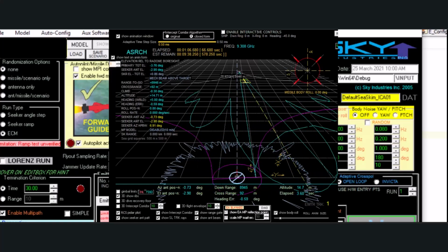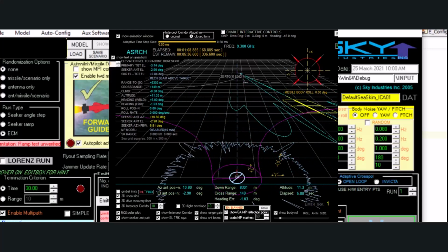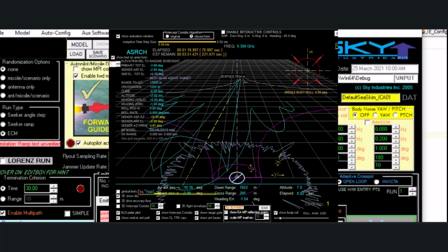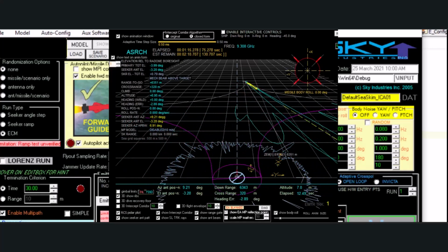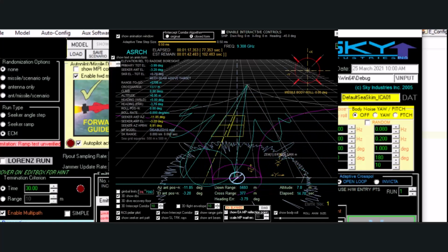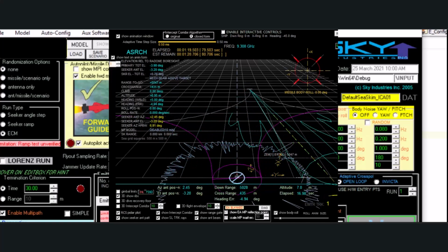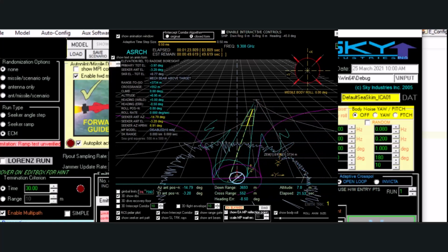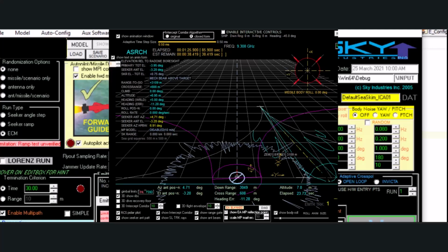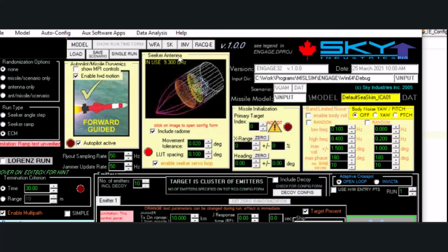But you have to design those yourself. And the default is right, I think. But if you wanted to choose your angle sweep and range sweep, you have to get enough power on the target, so you can't be sweeping too fast. You don't want to sweep so that the half power beam width of the seeker moves faster than the range gates can sweep, right? That's the thinking part, the missile designer part. So if there's no target, it does an angle search and volume search to find something, and when it finds something, it behaves in a normal way.